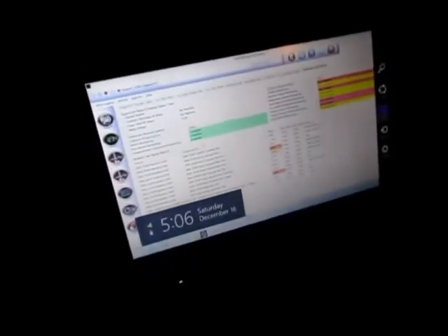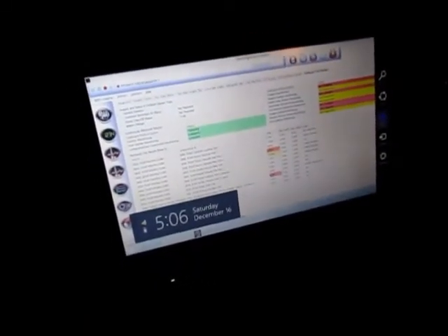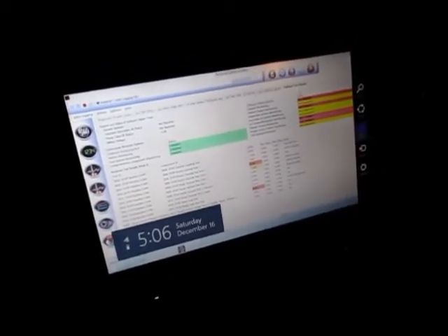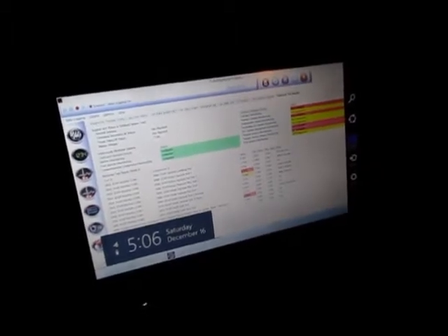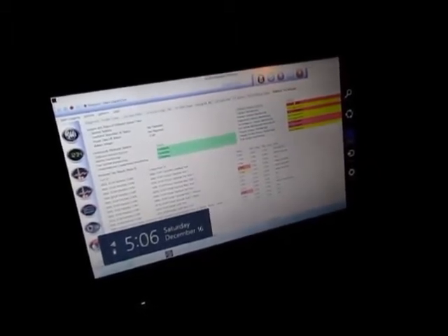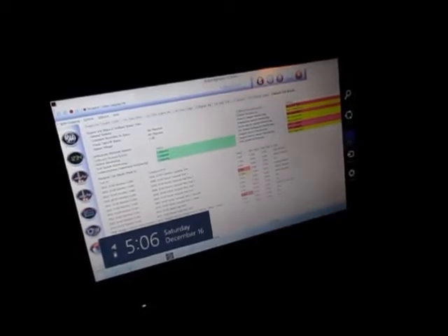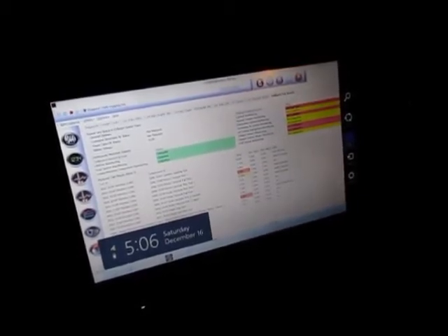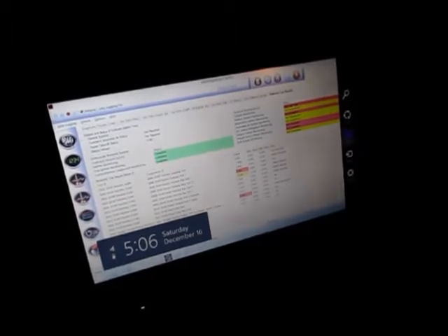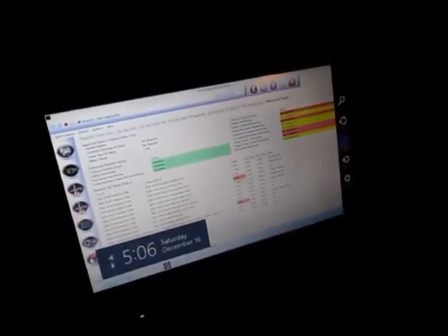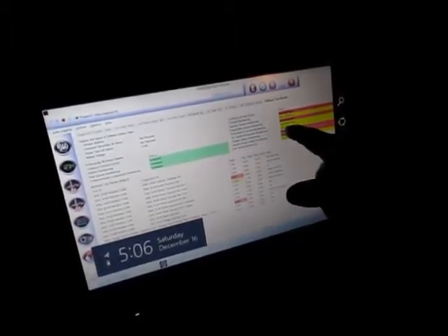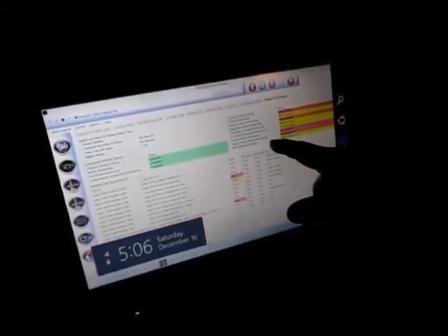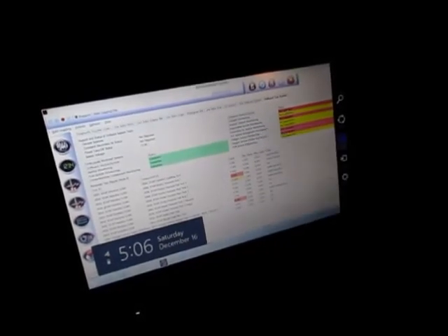Okay, so our misfire monitor is complete, and there's no misfires. When we cleared our codes, our oxygen sensor heater, evap, and catalyst monitors are not ready yet. They're not complete. You've got to drive the vehicle long enough to run the automatic tests on the catalyst monitoring system, the evap system, and the oxygen sensor.